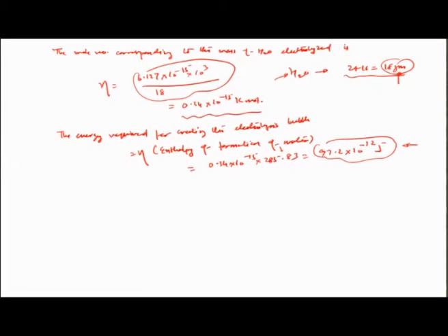Now, let us look at the thermal aspect and what is the kind of energy needed for it, and then we will try to calculate some efficiencies, particularly the electrochemical bubble formation efficiency and the thermal bubble formation efficiency. So, let us suppose at the standard temperature pressure condition, the specific volume of water is reported as 1.0029 times 10 to the power of minus 3 meter cube per kg.